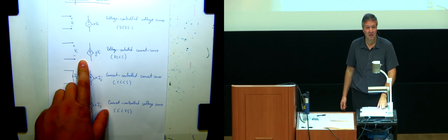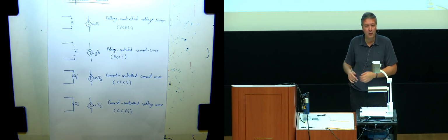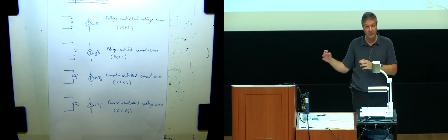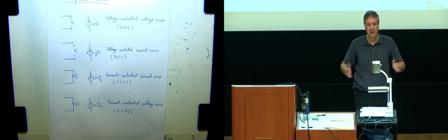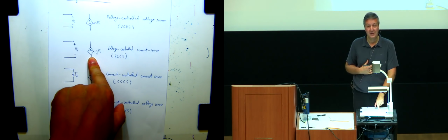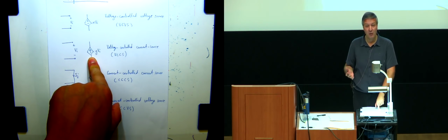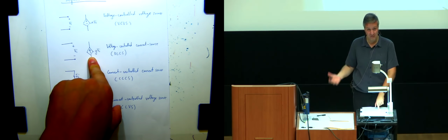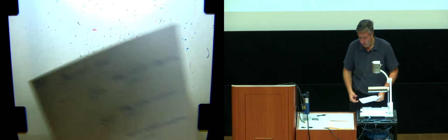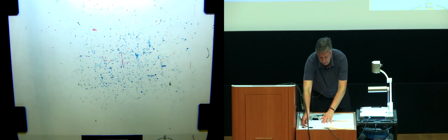You'll have it, I think, on discussion or homework. For you, it's just a model in a circuit, and you can apply KVL, KCL, the 7-step procedure, the magic quick procedure that I did last time. All of these analyses apply. You can apply superposition. Of course, in superposition, you cannot null this source because it is a dependent source. In equivalence, you also cannot null this source. Just keep that in mind. This is why I defined them, so we can know about them and do things appropriately.